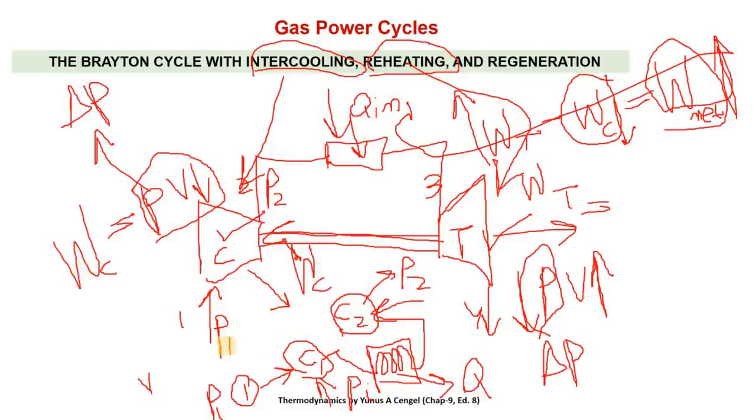So this particular point, if it is not clear, we shall be discussing it in the next chapter, which is about compressor, and there we shall discuss it in much more detail, and we shall also solve some numerical problems, that if we replace one single compressor with two-stage compression with intercooling between these two, the overall work input to these two compressors will be less compared to one single compressor for the same pressure rise, P1 to P2, right?